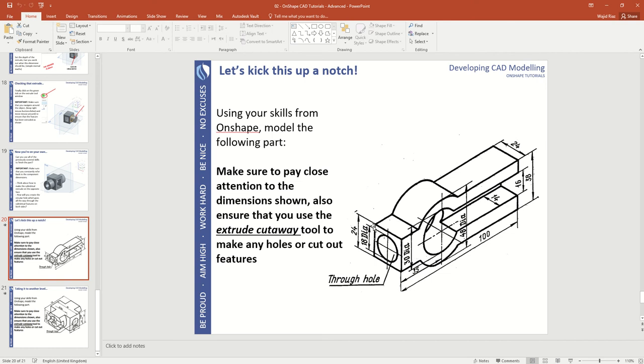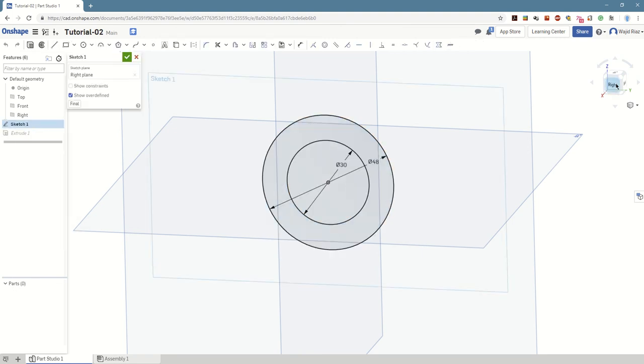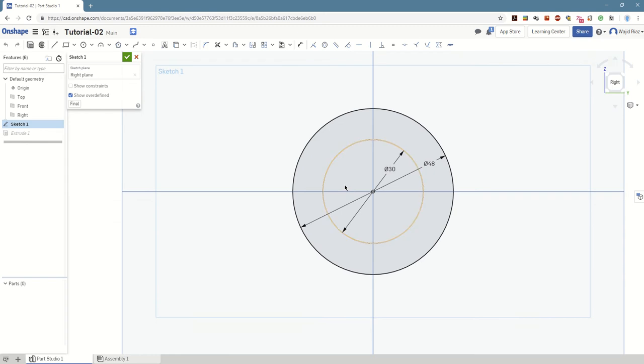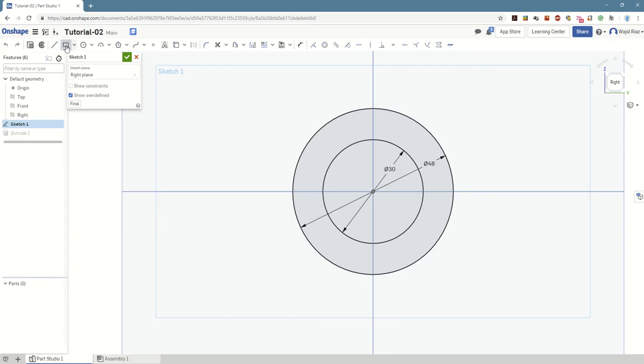dimension, we've got a 24mm height here, which sits in the middle. And again, it could be that the way that you model this is very much like going back to our initial sketch and making adjustments. So I know that I've got this rectangular section sticking out here. We know that it has a distance of 35 coming out from the center of our circle. So that's going to be 35 going out, and then 25mm high. So let's create our rectangle.